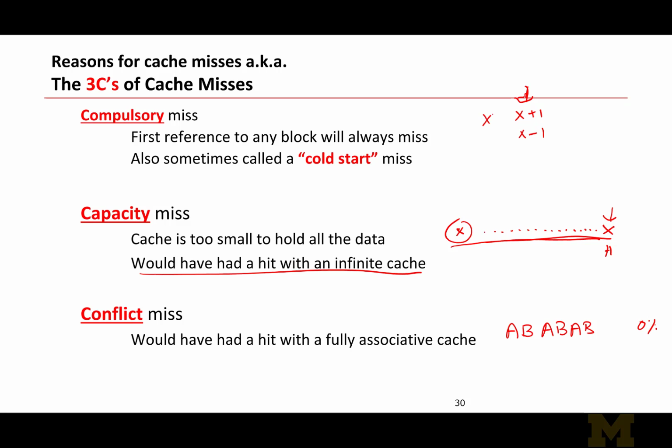And the reason why we are incurring all these cache misses is not necessarily because of lack of cache capacity. It might very well be the case that you had enough cache capacity, where you had plenty of cache lines sitting around, but they're not being utilized. But the cache blocks A and B happen to map to the same cache line and conflict with each other.